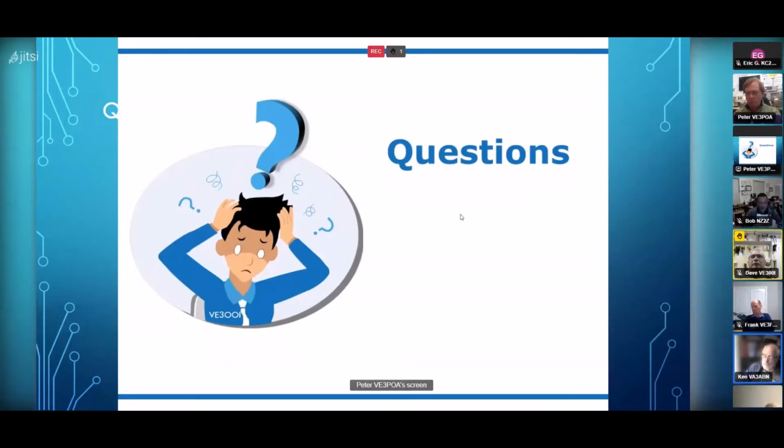Like you said, the output was rated at flat to 0.1 dB, and you were getting like 1.3 or 1.4, something like that? Yeah. So I'm just curious, does KiCad not have a function? First, I guess, do you think that's related to the layout of the board? And if it is, does it not have functions where you can do strip lines and 75 ohm traces or 50 ohm or whatever? I wonder if that has any effect, because you're getting some pretty good performance here, right?